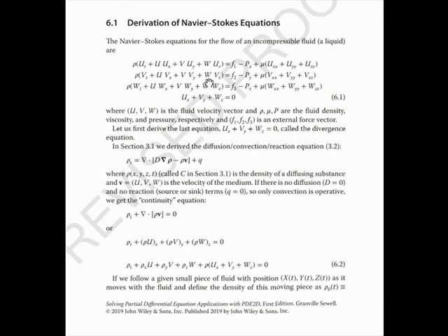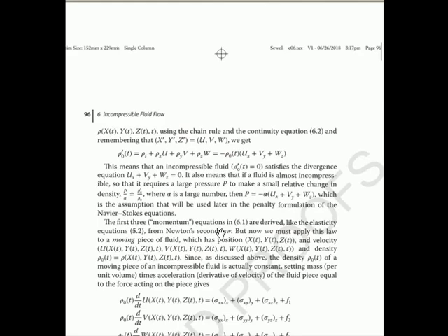So we're going to have to develop a trick, and there are 2 tricks we're going to use. And the first one will work for 2 or 3 dimensional flow, so let's talk about it first. It's called the penalty method, and that's what we just got through talking about. Basically, we use the equation that I just showed you here, that we just replace the pressure by minus a large number times Ux plus Vy plus W sub z.